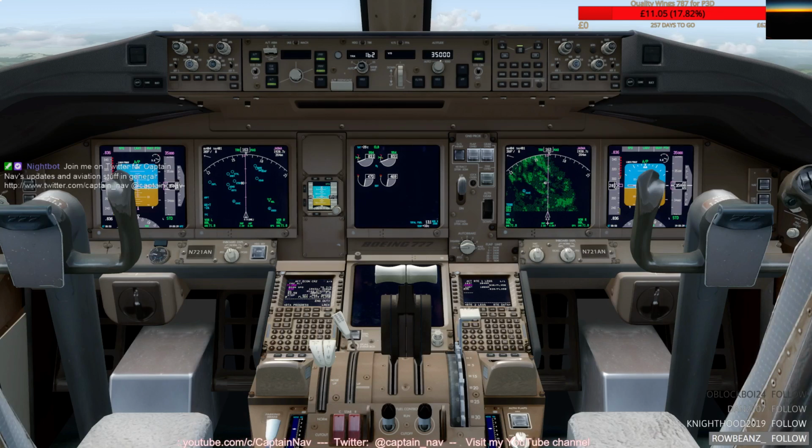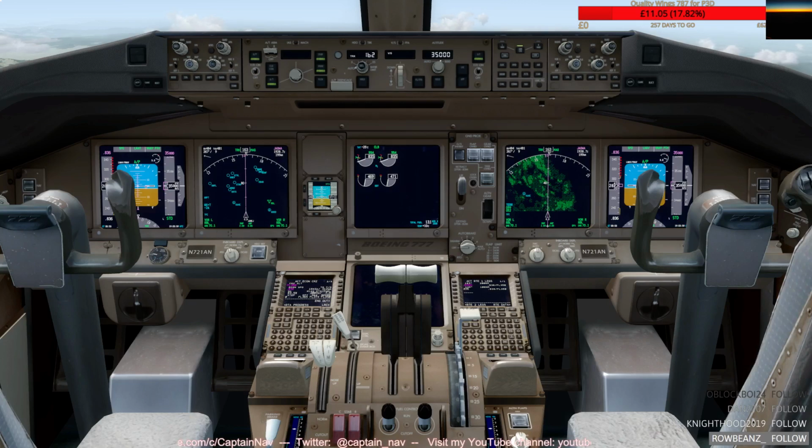But then once you're further down and you don't follow strictly the arrival because you're on radar vectors or something, that's when flight level change or vertical speed gives you a little bit more control over the rate of descent, above all with vertical speed, because you can adjust exactly your rate of descent. You can set, I don't know, 500 feet per minute, 800 feet per minute. During the intermediate descent as well, if at some point you're a little bit high, then you can use flight level change, use some speed brakes, and that will give you the best descent rate possible.